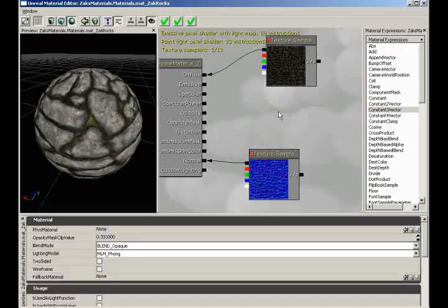We're not going to use a constant color and apply it to our entire material. What we want to do is selectively add specularity to only certain areas of the rock and not to others. To do that, we need some form of a mask. We need a texture that is black in the areas of the moss and is white or lighter. I'm not going to say white because white might be pushing a little bit, but lighter than black over in the other areas where the rocks take place.